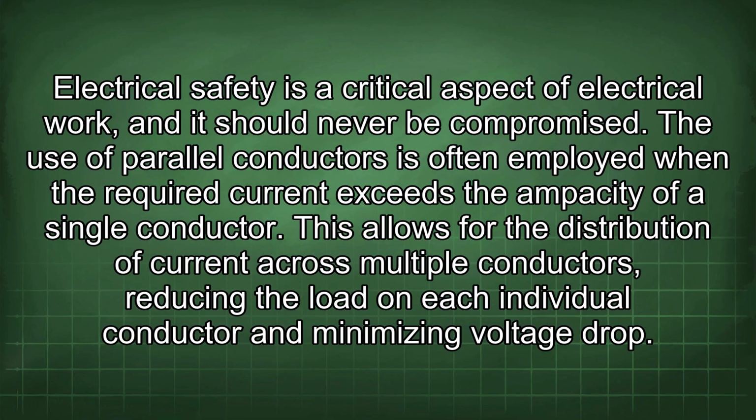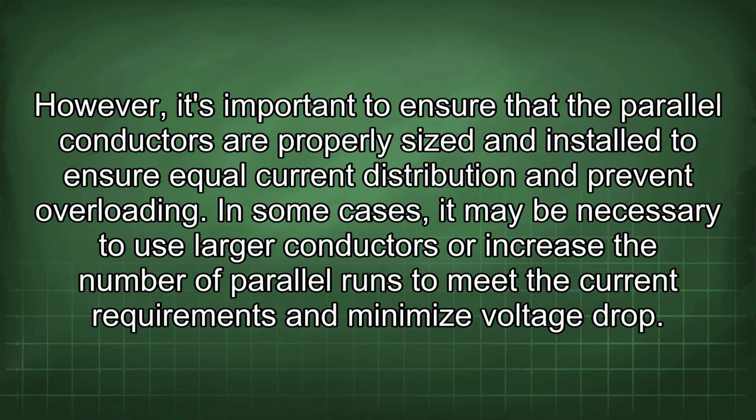The use of parallel conductors is often employed when the required current exceeds the ampacity of a single conductor. This allows for the distribution of current across multiple conductors, reducing the load on each individual conductor and minimizing voltage drop. However, it's important to ensure that the parallel conductors are properly sized and installed to ensure equal current distribution and prevent overloading. In some cases, it may be necessary to use larger conductors or increase the number of parallel runs to meet the current requirements and minimize voltage drop.